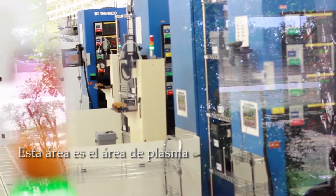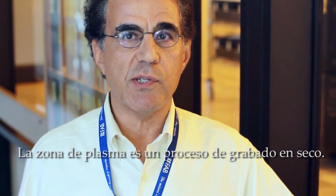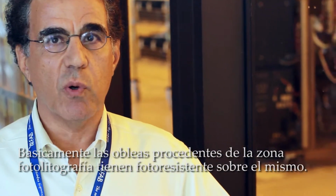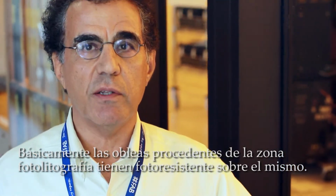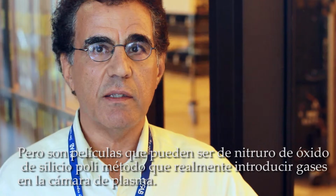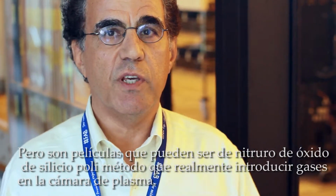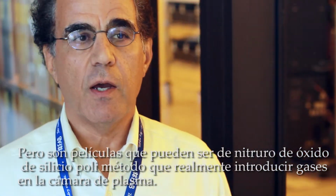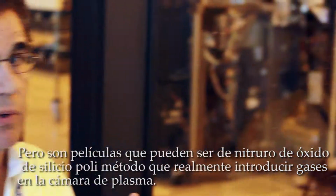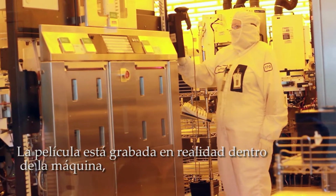Okay, this area is our plasma area. The plasma area is a dry etch processing. Basically, the wafers coming from the photolithography area have the photoresist on it, but there are films that could be oxide, metal, polysilicon, nitride, that we actually etch. We introduce gases into the plasma chamber, and the film is etched in the machine.